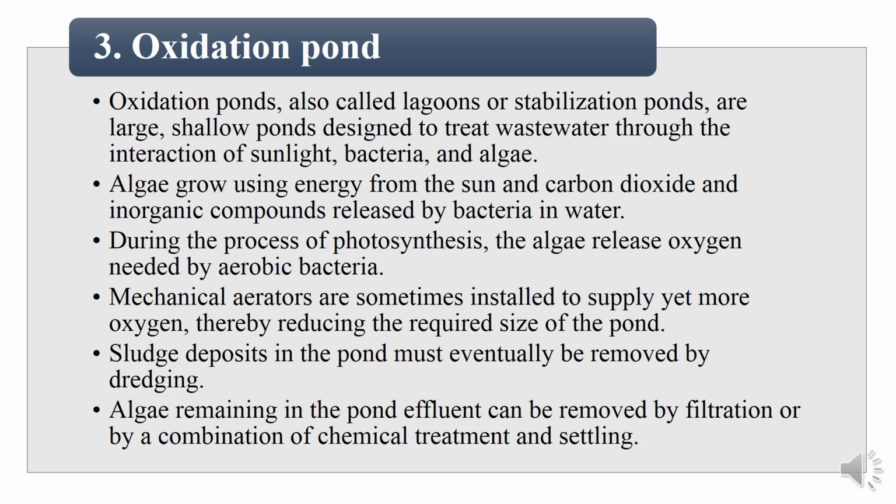Mechanical aerators are sometimes installed to supply yet more oxygen, thereby reducing the required size of the pond. Sludge deposits in the pond must eventually be removed by dredging. Algae remaining in the pond effluents can be removed by filtration or by a combination of chemical treatment and settling.